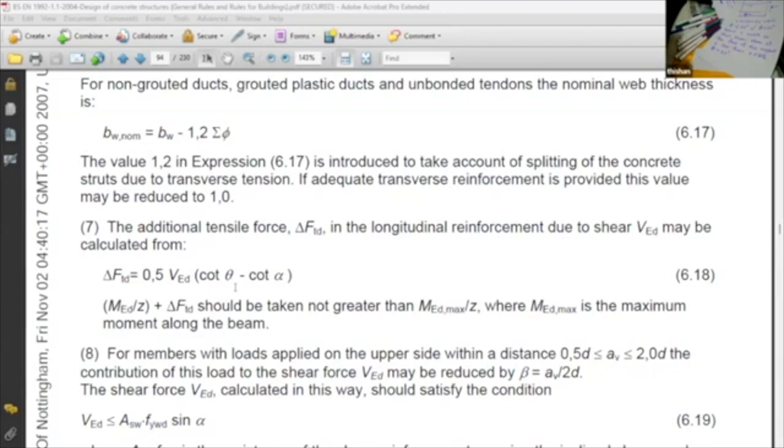Right. So you have to be very careful in shear design. When you are curtailing, especially in Eurocode, the curtailing methods are very different. So you have to curtail the smaller bars, not the big bars. Big bars must be running, otherwise you can't provide this shear capacity. Equilibrium cannot be provided easily. Got it? Yes, sir.